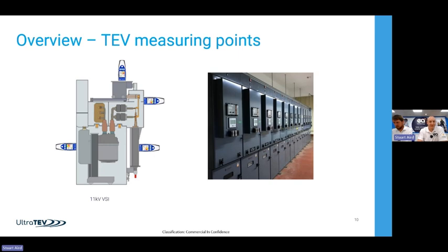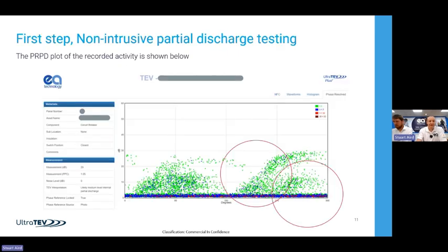And we normally take it from these primary components: the circuit breaker, cable box, CT chamber if it's separate, the VT on the top, any piece of steel really on the switchgear, probably the end of the busbars as well at either end, and whatever access we can get. So each individual piece of steel we should be going around and taking a measurement from. In this case, we've done the whole switchboard, and we found some elevated PD levels on one of the panels.